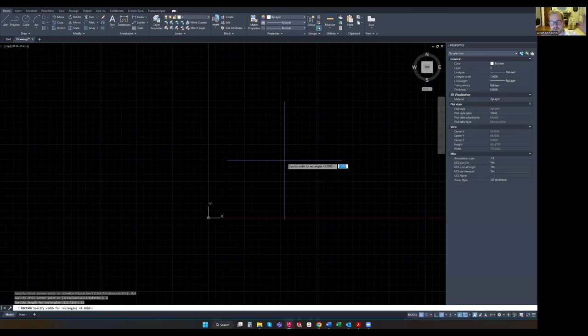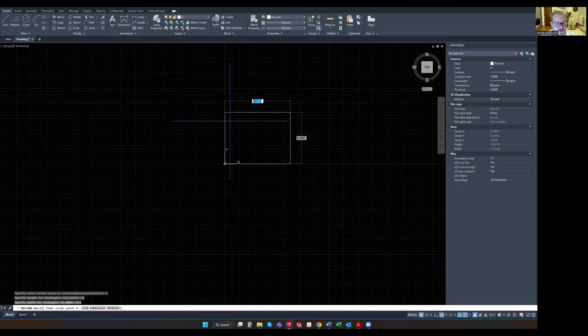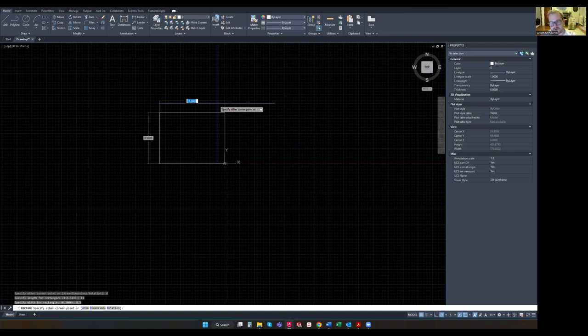I was doing coordinate points, comma. No, so you want to type in 11, enter, 8.5, enter. Sorry about that. Now it looks really small because I was zoomed out quite a ways. So just zoom in, and then we have the same situation. So I haven't clicked again after I entered those dimensions. And remember, that was the 11, enter, 8.5, enter, not comma, because we're not doing coordinate points for the second point.